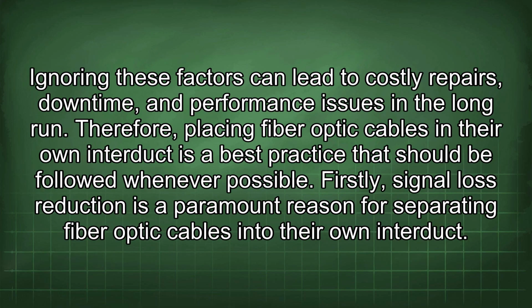Ignoring these factors can lead to costly repairs, downtime, and performance issues in the long run. Therefore, placing fiber optic cables in their own interduct is a best practice that should be followed whenever possible. Firstly, signal loss reduction is a paramount reason for separating fiber optic cables into their own interduct.